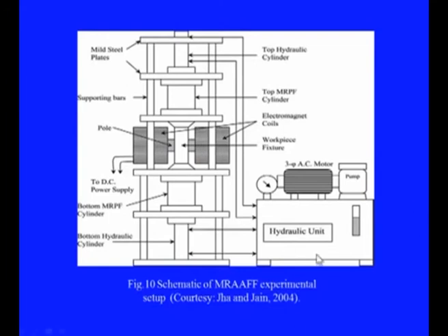In this process, rheological properties of an abrasive laden medium, also called smart magnetorheological fluid, is controlled using an external magnetic field. It imparts better control of the process behavior due to better control over the abrading medium's rheological behavior. This is the schematic of this process. This is where the magnetic poles are, and this is the workpiece fixture, and these are cylinders in which magnetorheological fluid is stored, and this will be pushed from one end to the other cylinder where the magnetorheological fluid will be collected, and then the process will continue. The other controls and necessary measurement devices are also shown.